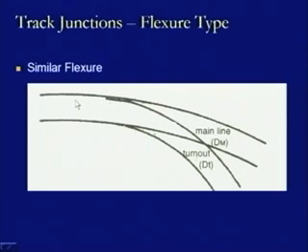We are providing a flexure of the turnout also in this direction only. The only thing is the flexure by which it is being taken a turn is a little more than what is being provided for the main line, and only then is it going to differentiate. So, if we look at this diagram, what we can observe is that there is one pair of point and switches being provided at this location, and there is one crossing or V or a frog being provided at this location.